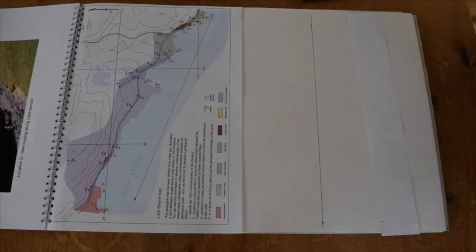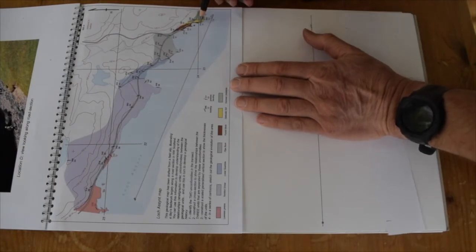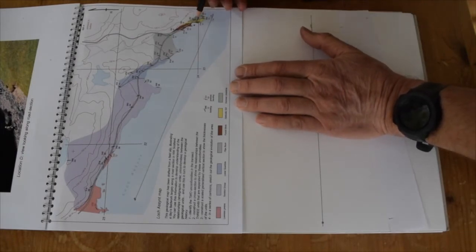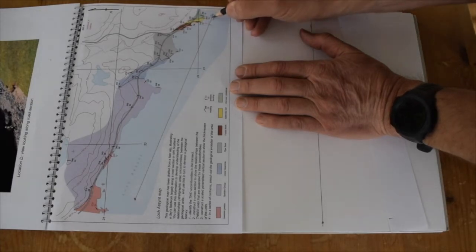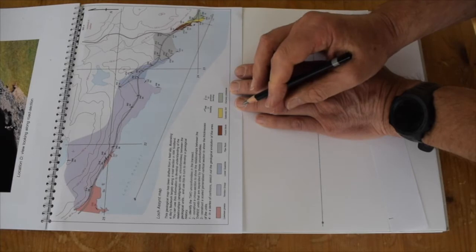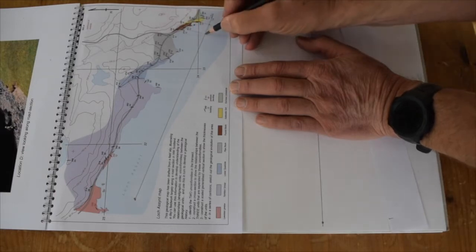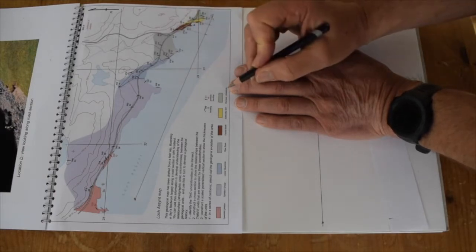Now let's continue, and we can put the base of the Saltarella grit in now. So here it is at the side of the loch, and we can project it along its strike to here, and it projects more or less parallel to the boundary of the Saltarella grit and limestone. So that's where that point, fucoid bed Saltarella, intersects the profile. We can do the same with the pipe rock, take it out along its trend, so that gives an outcrop width to the fucoid beds.